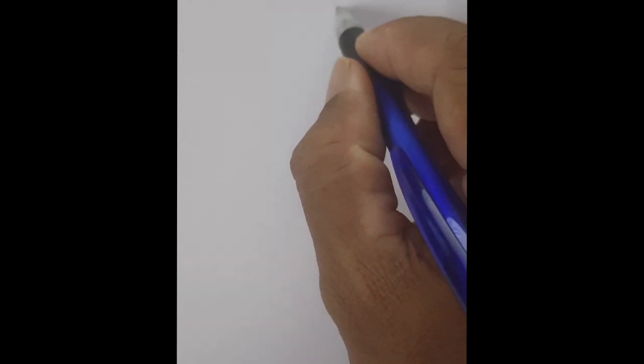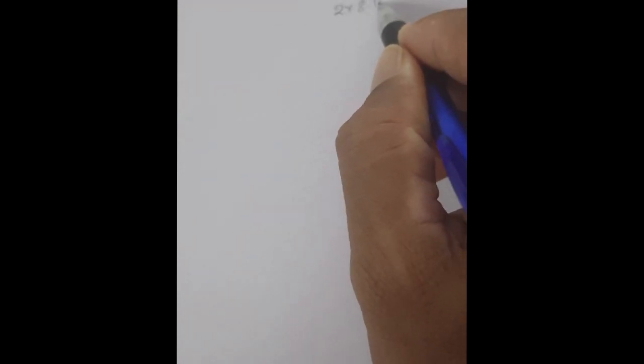So now it is a 20 mm side. So you just multiply 2 into 8.163. Okay, so approximately we need 16.326 mm as one side length or one base edge length. Okay, so to complete this one, I am going to draw a circle of 16.32 mm. Then I am going to construct the hexagon by using the arc method.